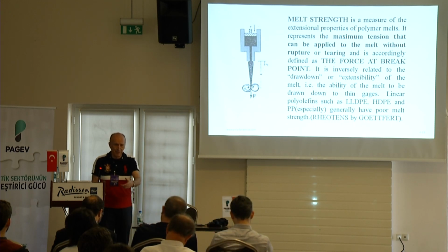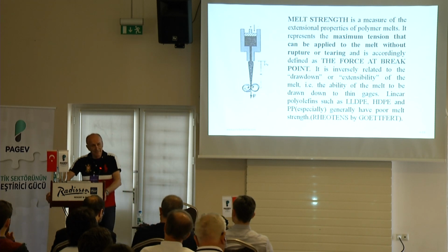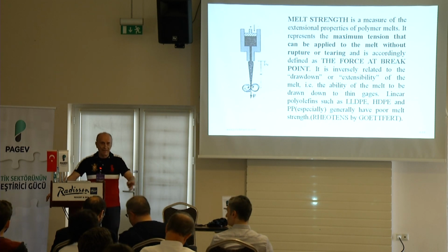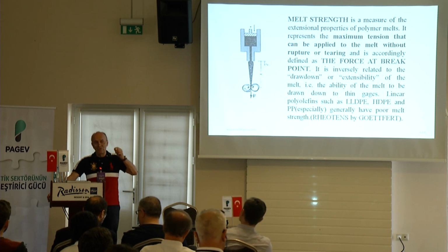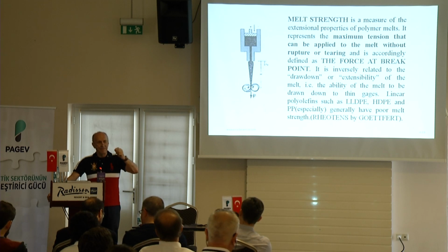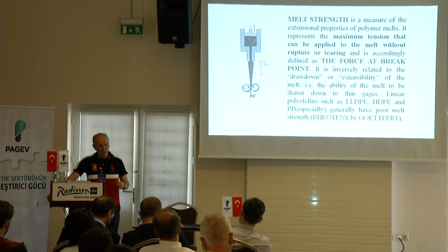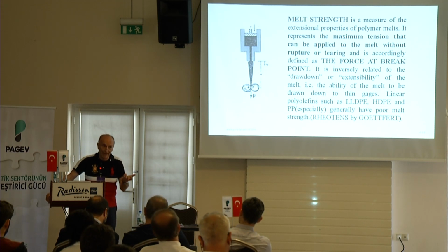I think the company of Mr. Eroğlu is in thermoforming business, right? Right. Well, in that case, elongational viscosity or melt strength is very important. For example, if you have low melt strength, the cups or whatever they make at Mr. Eroğlu's company will break. And it might be difficult to thermoform and get a good shape if it's too high.